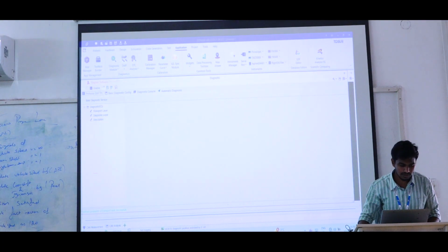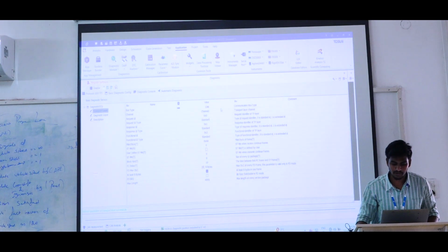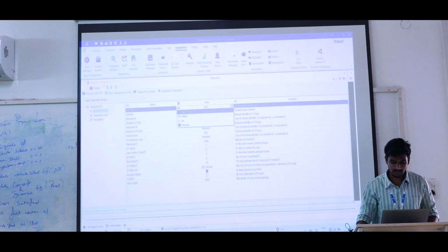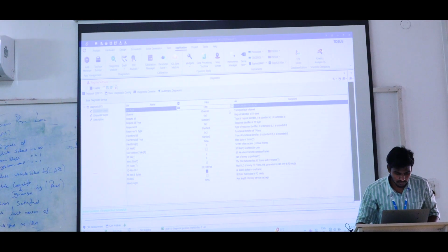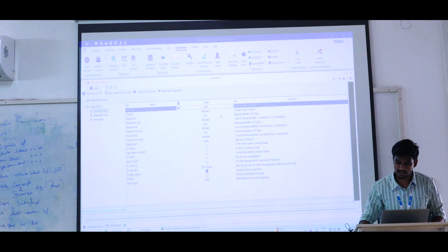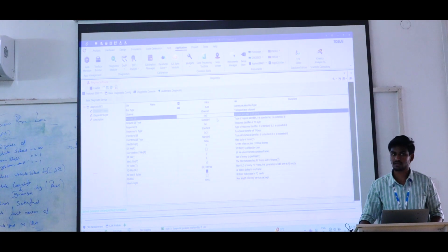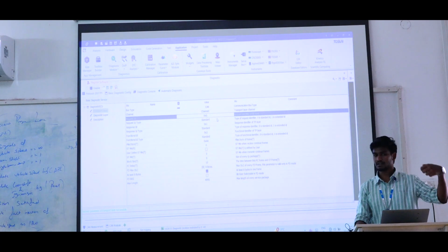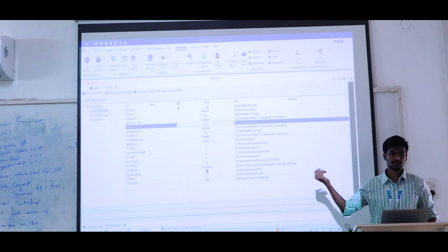For example, in the protocols, transport layer, we need to set what kind of bus channel we are going to work with: CAN, LIN or Ethernet. What channel you are working with, what request ID you mention, what ID type you are going to work with, standard CAN or extended CAN, and what response ID it is going to transport for us.